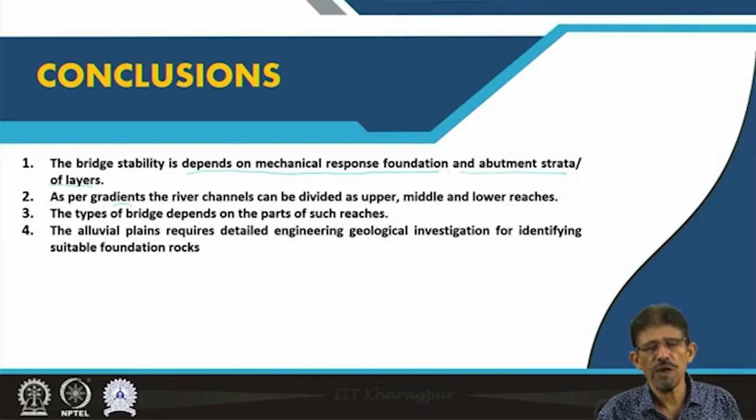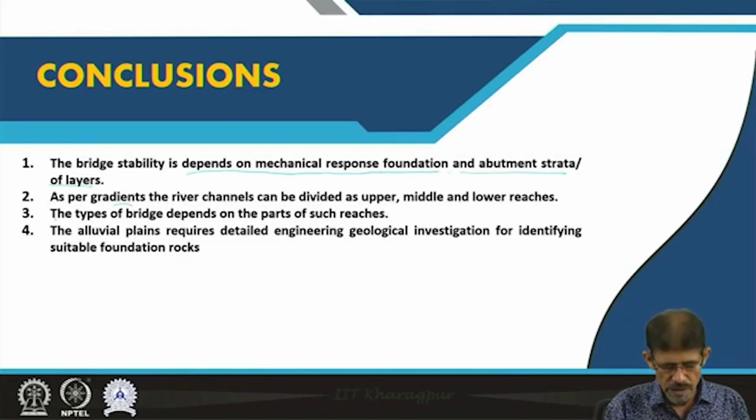geological, engineering geological and geotechnical investigations through geological mapping, preparation of sections, exploratory drilling, application of seismic techniques and other techniques related to ground penetrating radar, etc. These are utilized for subsurface investigations, with laboratory work to determine strength, modulus, Poisson's ratio, cohesive strength, shear strength, angle of internal friction, etc. The types of bridge depend on the part of such reaches.